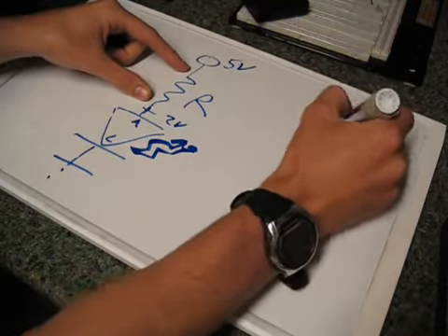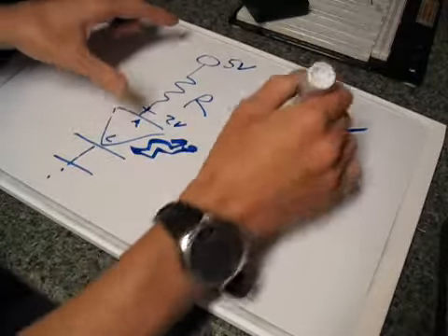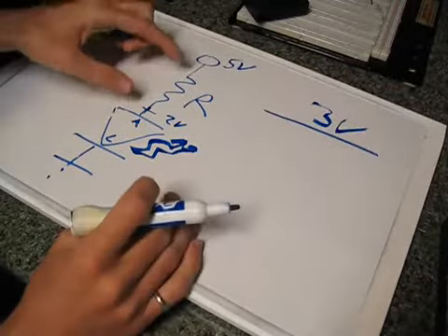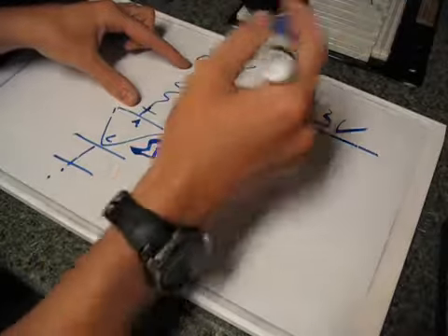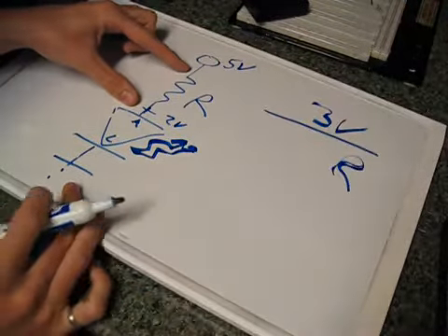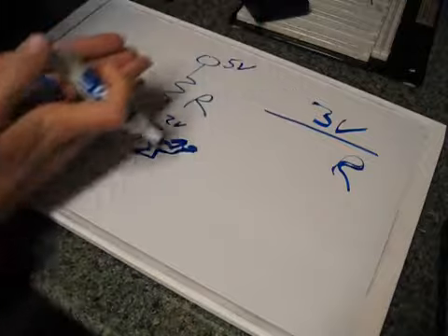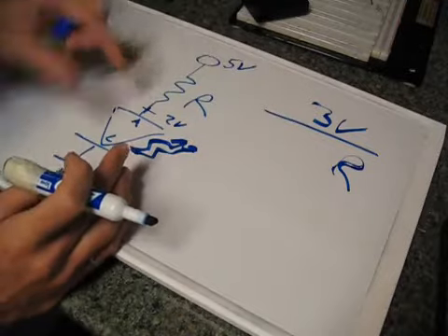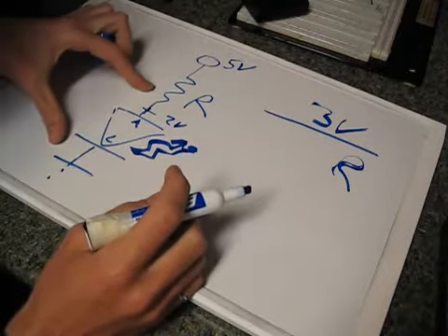So now we're looking back at Ohm's law again. We need to solve what R is. Do we have the current? Yes, we do, because the current in a series circuit is the same through each component, and we want it to be 20 milliamps.